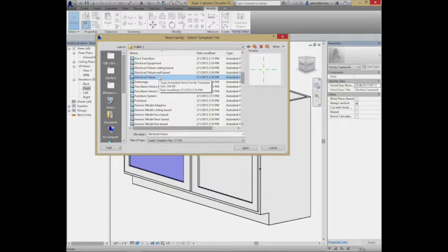Ceiling-based fixtures need to live on a ceiling, so you have to have a ceiling to put them into. These lights in here, the big troffer lights, that camera which is hanging from the ceiling, these speakers, these are all ceiling-based objects. And how does that actually work? As we're creating them, you have a little template or a placeholder ceiling. You define your object, and then as you place your object on a ceiling, it'll insert it into whatever ceiling you put it on. Okay, so we have ceiling-based objects.